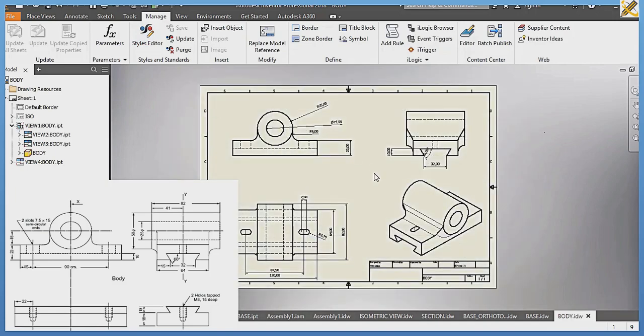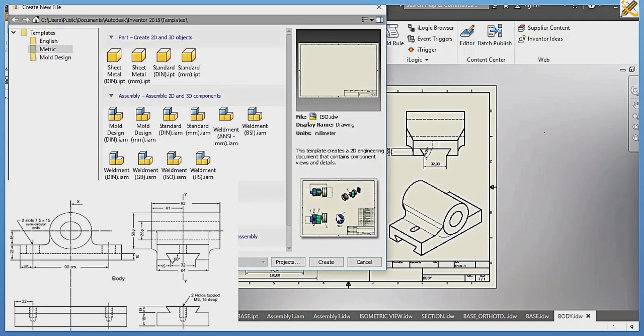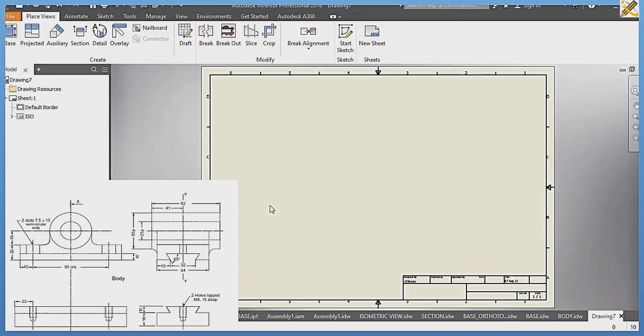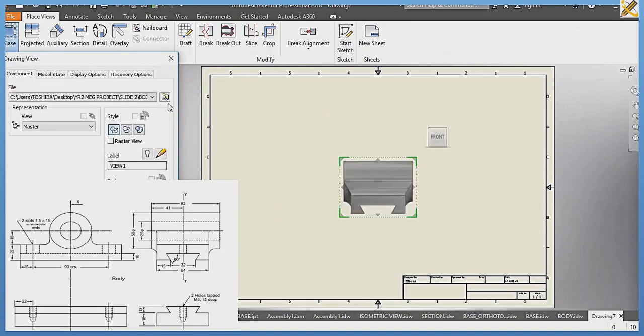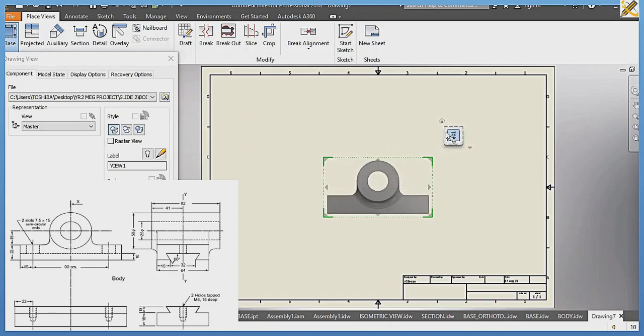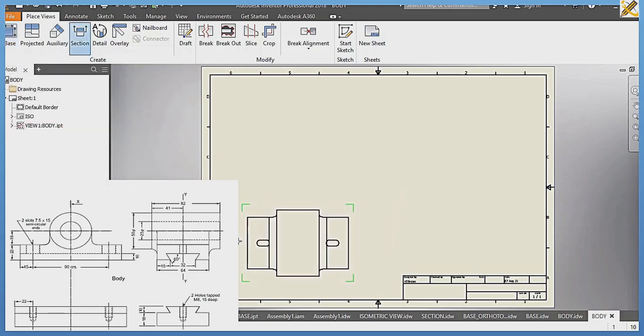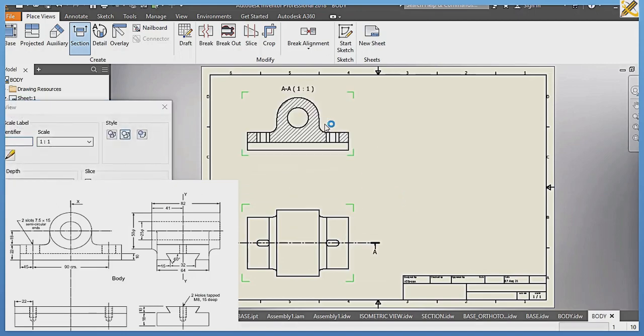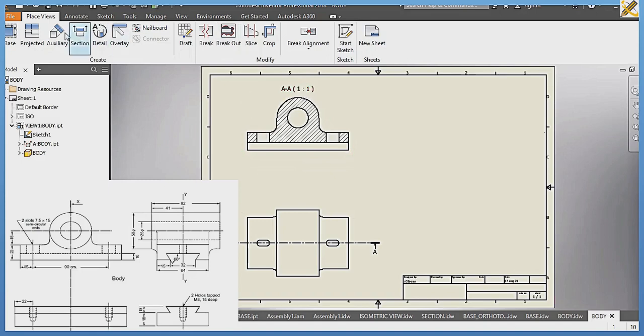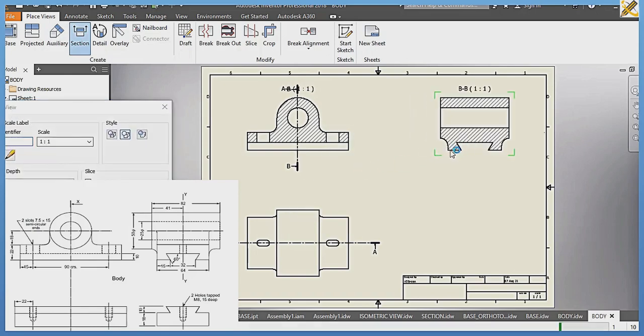That's it. So then coming to a new worksheet, I'm creating the sectional view for our body. Alright, so coming right here, I already have the body there. So facing this direction, then coming down right here, that is the plan, coming to the bottom here. So I am creating my section in third angle orthographic projection. Alright, so the plan is at the bottom. So cutting it from the plan, I'm having my front view. Then if I also apply my section on the front view in this manner, cutting it this way, towards the end view, I am going to have this as my end view.